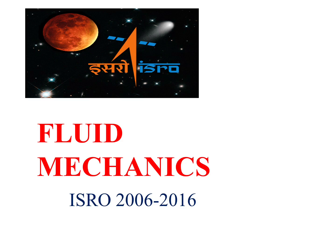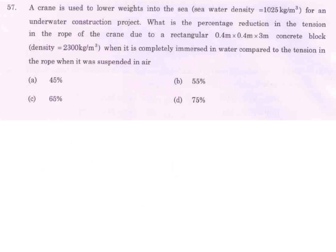This is Fluid Mechanics Part 18, ISRO question paper from 2006 to 2016. A crane is used to lower weights into seawater, density given 1025 kg per meter cube, for an underwater construction project. What is the percentage reduction in the tension in the rope of the crane due to a rectangular 0.4 meter into 0.4 meter into 3 meter concrete block, density 2300 kg per meter cube, when it is completely immersed in water compared to the tension in the rope when it was suspended in air.